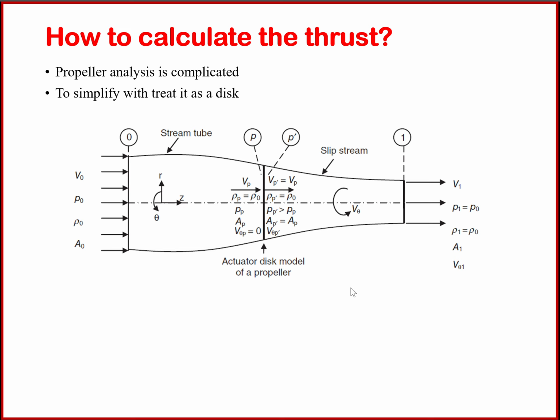Analyzing the power and force in a propeller is very complicated because the geometry of a propeller is very complicated. But if you have a system level perspective, meaning that if you look at just the energy transfer in the system, we can simplify the propeller analysis and treat the propeller as a disk that adds energy to your fluid system. If you apply this lens, you can find the force of the propeller, or force of the disk.